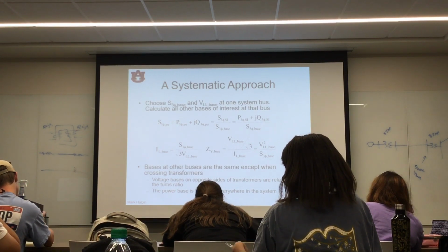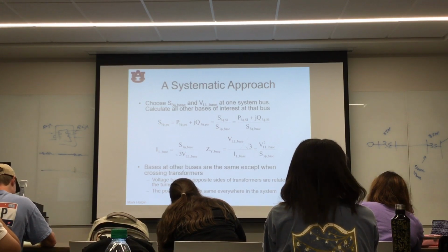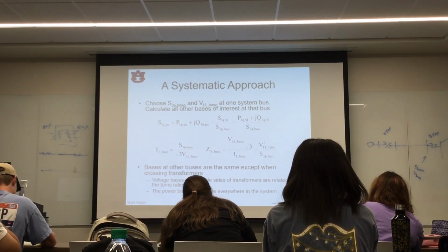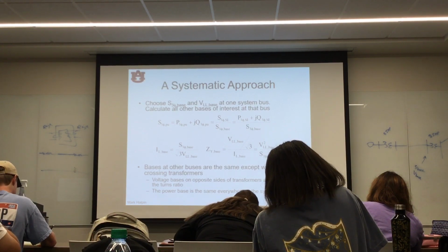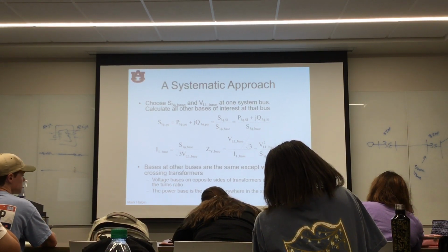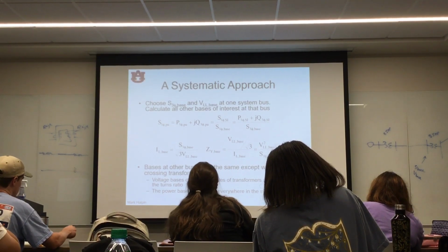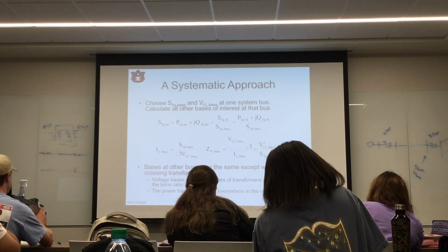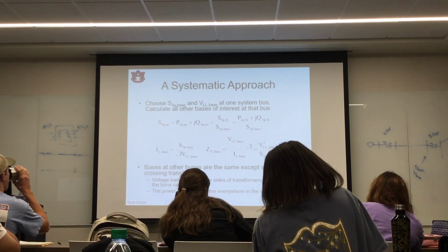Sometimes you will try to apply that formula, and it's a single-phase problem that I'm giving you to work. Sometimes you will forget that it's the line-to-line voltage base in the numerator. Sometimes you will forget that it is three-phase power in the denominator.